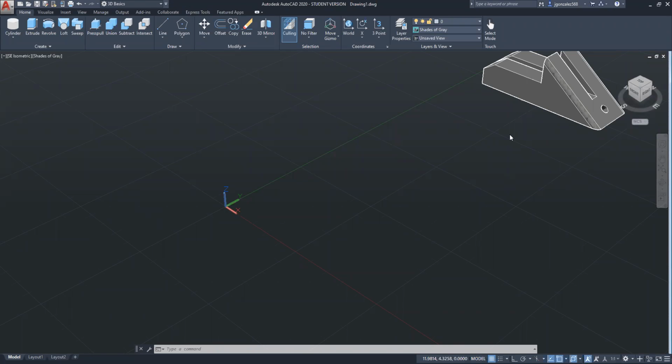Yeah, so open the AutoCAD 3D template, then go to the little gear down here and choose 3D Basics to change the menu layout. Then we'll go over some of the basic functions real quick. Build a few things.